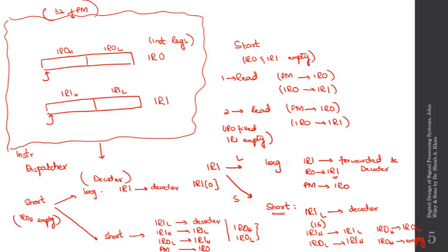How's that? Because we are saying that we have 32-bit data, we will pick this whole register and send this 32-bit data out. Because this data has been executed upon, it is no more useful to me. It's empty, for our reckoning. The only viable data that is left is in IR0 low. In such a case, the data available in IR0 low will be directly fetched into IR1 low. Now we are left with 24 bits that are empty right now.